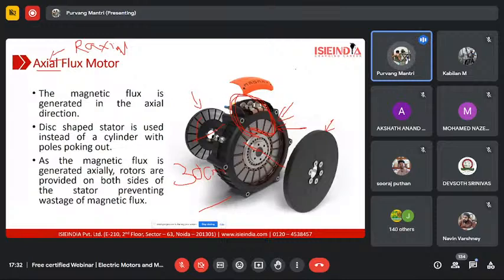You might have seen the video of the Hyundai Ioniq, I suppose. I don't remember the term, but you might have seen how that particular vehicle has a high steering angle, because they were using servo motors mounted directly on top of their wheels, and that servo motor can make the wheel rotate about 90 degrees. Okay, one wheel rotating at 90 degrees. And that type of steering system had an axial flux motor mounted on it. I've actually made a video about it, so you might have come across it. So yeah, these are axial flux motors.